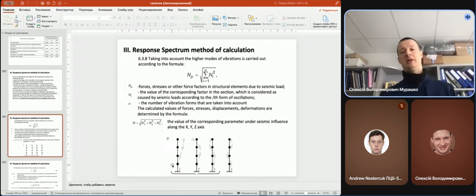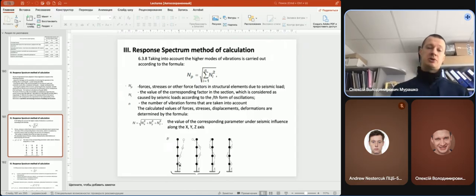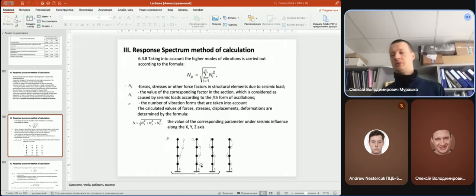We will get the square root of the sum of squares of this seismic force, this, and this seismic force, without taking into consideration that it is possible that this mass during the earthquake will go in this direction, without taking into consideration the directions, only the square root of the sum of squares.